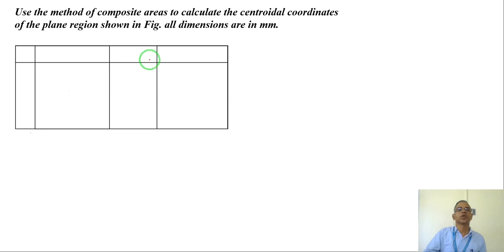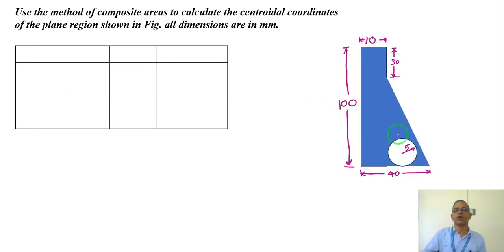Now let us see what if I remove area from the given cross section. So now I have the same dam, but there is a circle cut there. In the concrete I can have a hole along the length of the dam for some maintenance purpose. Now how will I find out the centroid? The centroid will not be the same point, it will shift, right? Slightly to the left-hand side and slightly upward.